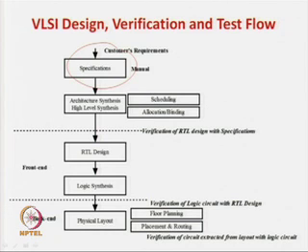Then we have seen that it can be coded in the form of Verilog or VHDL, some language in which we write down the specifications. Then we have to go for an architectural synthesis, that is scheduling, allocation and binding. That is, for a given specification to be realized, how we can optimally schedule the operators required in the given time steps, and how individual hardware operators are bound and allocated to these operations. So this was the high level synthesis part, which we have already discussed in detail in phase 1 of the course, which is on design.